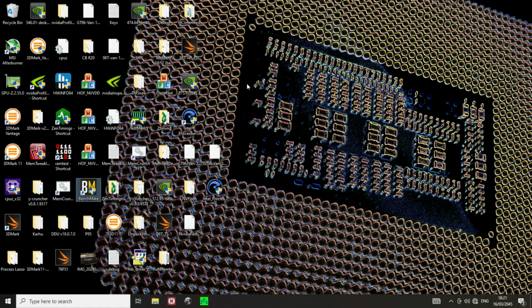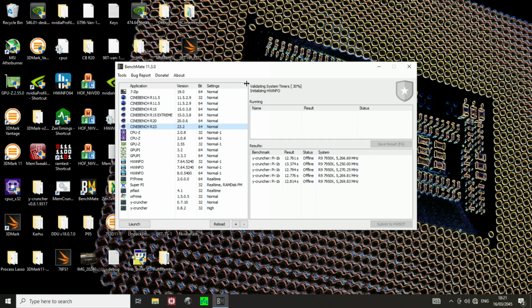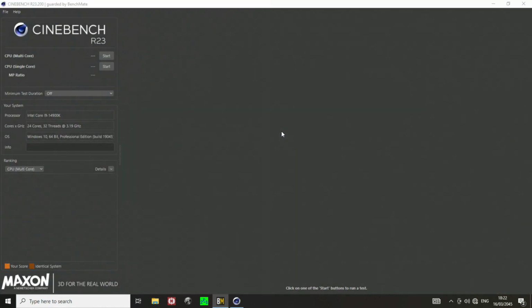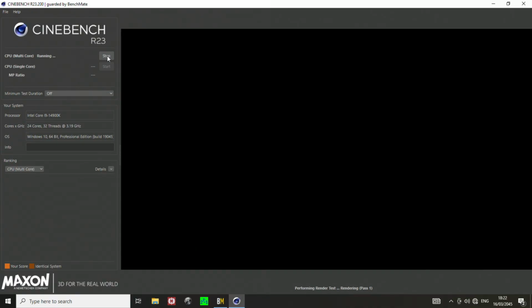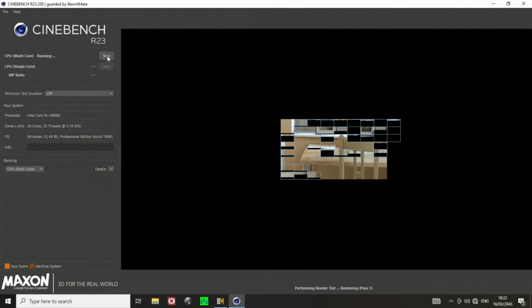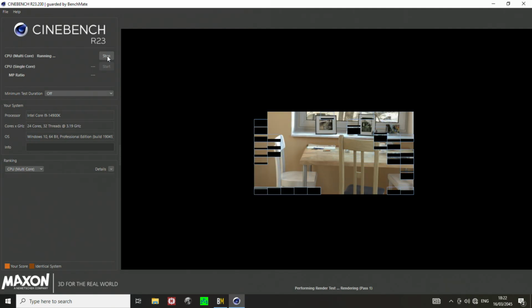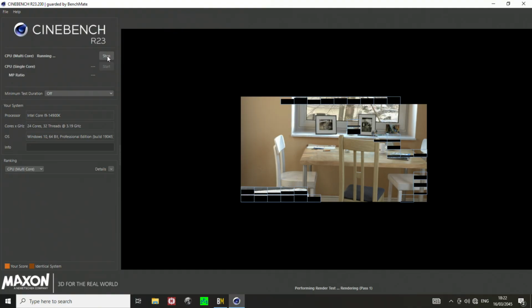If your priority is to get your single core and low core, low current voltages down, you want to use VID offsets. And the cool thing with 14th gen is that Intel actually gives you the ability to adjust the VID offset for every single frequency point. Personally, I wouldn't bother with that, because it'll take forever to tune correctly. But you do have the option to adjust your 6 gigahertz VID separate from your 5.7 gigahertz VID, from your 5.5 gigahertz VID, from your 5.3.